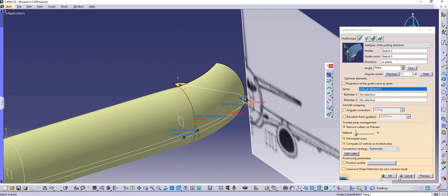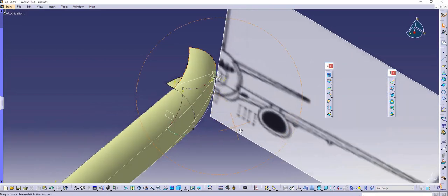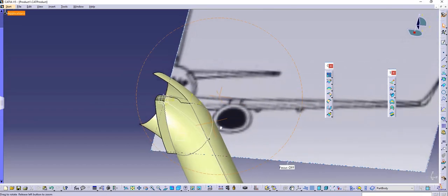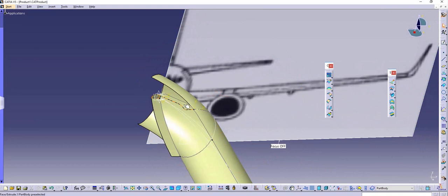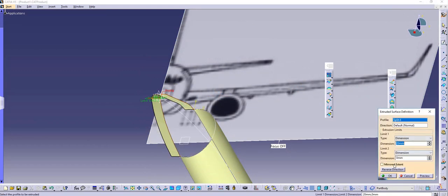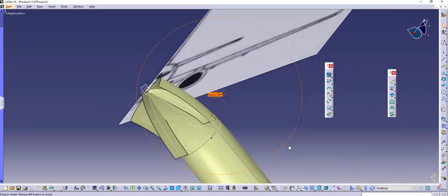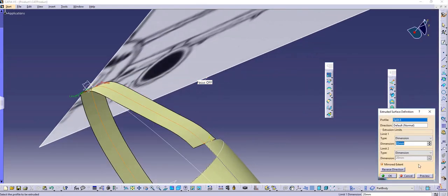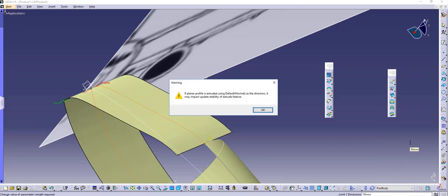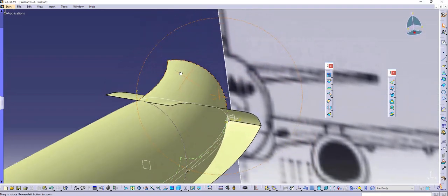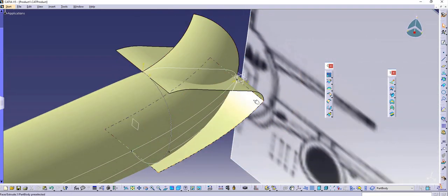I mean, if I intersect it, so let's say I'm going to click OK for now. Because I have this part right here, I'm just going to intersect it with this. It's going to give us the surface. So I'm going to mirror it both sides, and I'm going to increase it by, let's say, 50 on each side so that it properly intersects it. And then wherever these both intersect, I just want to get rid of the other part. So I can do that for sure.